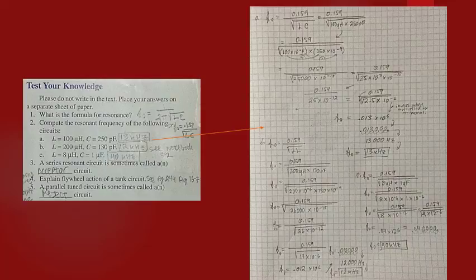But guess what? When current stops flowing, then the capacitor will again try to discharge in the opposite direction. And once again, if you discharge in the opposite direction, then the magnetic field will collapse in the opposite direction, and again, current will flow, helped out by the inductor once again, and this will charge the capacitor in the opposite polarity. And this cycle repeats itself over and over, so you get something of an AC current flowing within the circuit of the capacitor and the inductor.